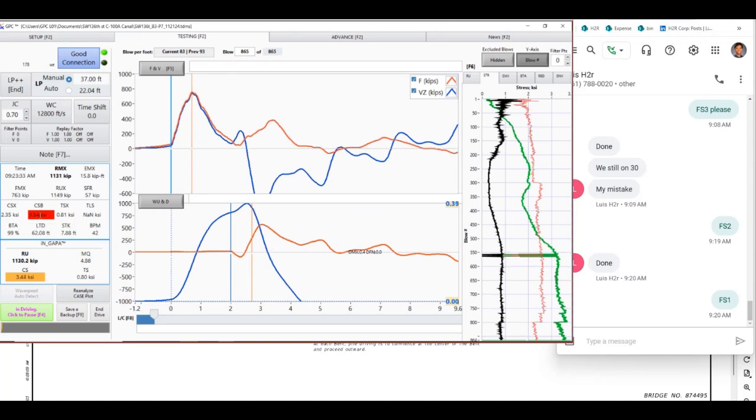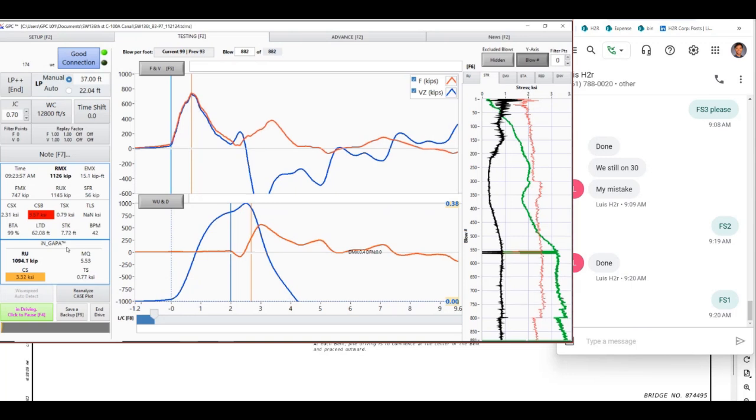The real stress limit, though, is about 3.8, because in Florida there's an equation to calculate the allowable compression stress based on the concrete strength and the pre-tension stress. If you use the formula, it's going to be around 3.8, but we put in 3.5.